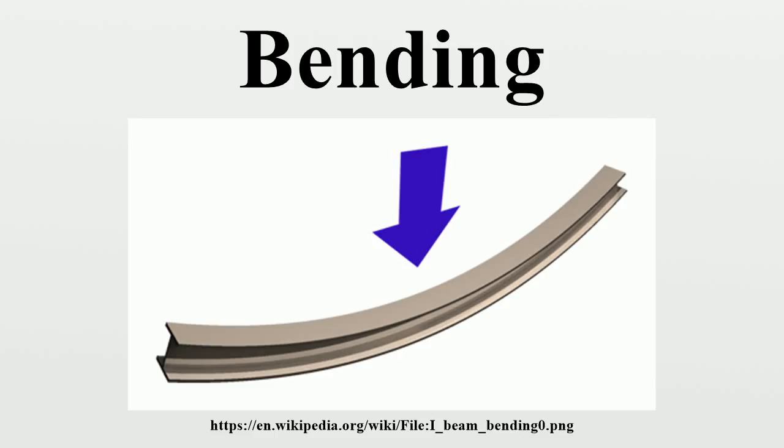Consider beams where the following are true. The beam is originally straight and slender, and any taper is slight. The material is isotropic, linear elastic, and homogeneous across any cross-section. Only small deflections are considered. In this case, the equation describing beam deflection under an applied transverse load, it can be shown, is the Euler-Bernoulli equation for beam bending.